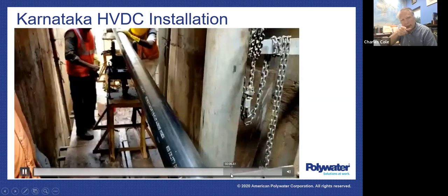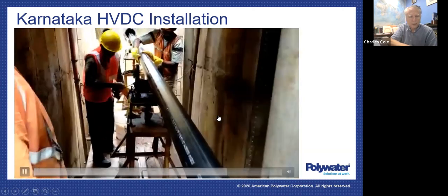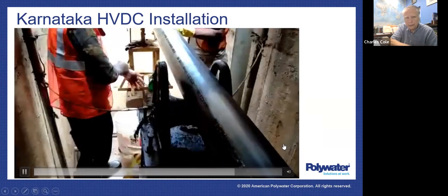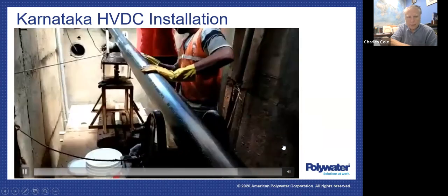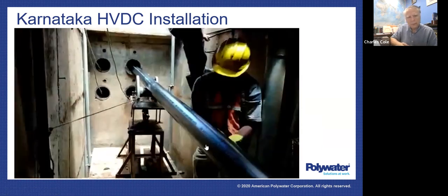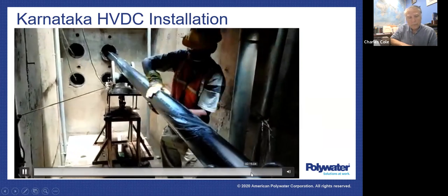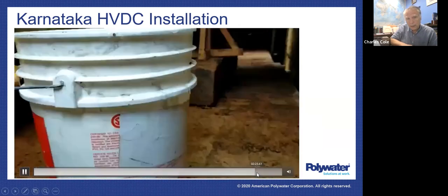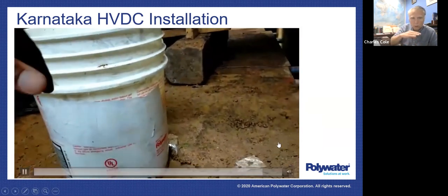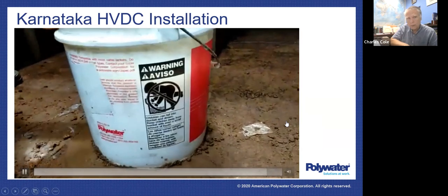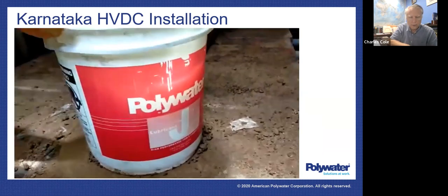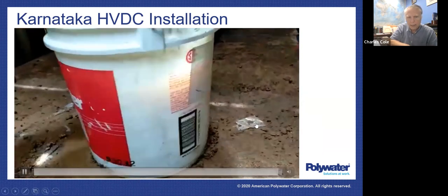So there you see the duct bank. You see the cable going into the duct. And what these people are doing here, they're applying lubricant onto the cable itself. They're slathering it. They're trying to cover the complete surface of the cable, because the cable inside the duct might come into contact not only at the bottom of the duct, but on the side walls or on the top of the duct. So spreading that lubricant around the total circumference of the cable is the right application.